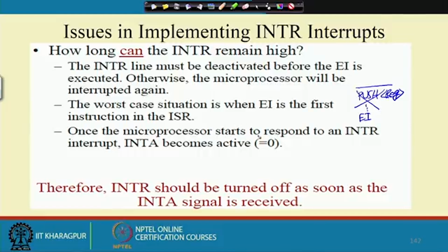It is a standard practice that the interrupt should be turned off as soon as the INTA signal is received. Whenever the device receives the INTA signal from the processor, it should turn off the interrupt line. That should be the practice followed.